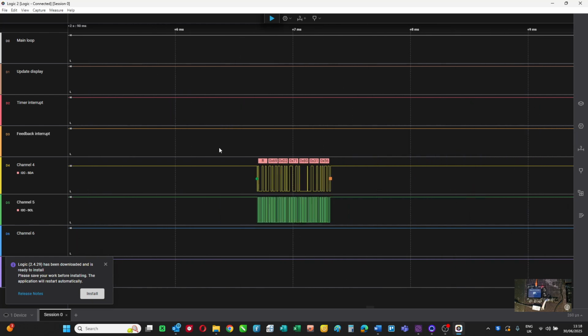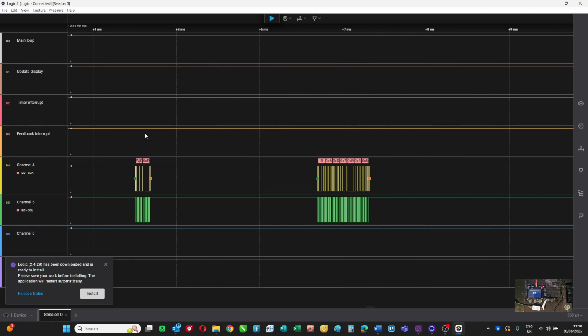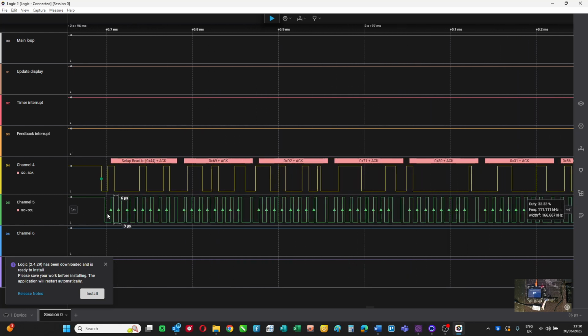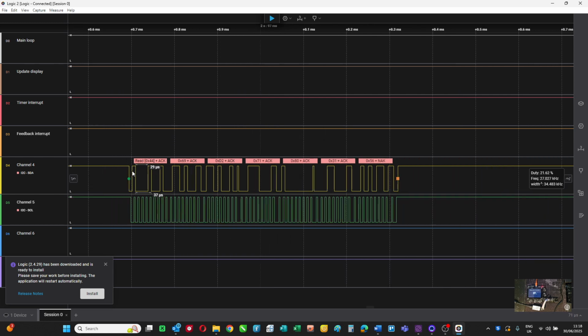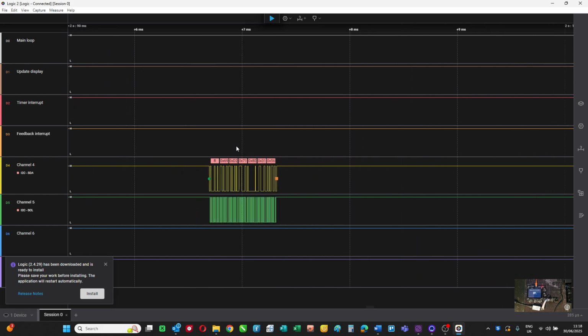But in this exchange, you can see from a systems point of view, you've got a request for information and a return for information. And from a data point of view, you've got a clock line and a data line. On the rising pulse of every clock, the data is valid. So that's when the chip knows when to sample the data. And it puts together the appropriate information.